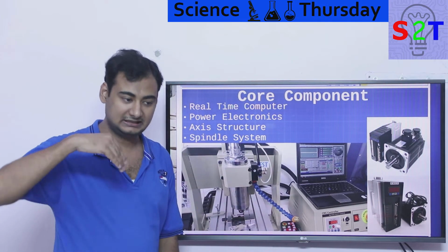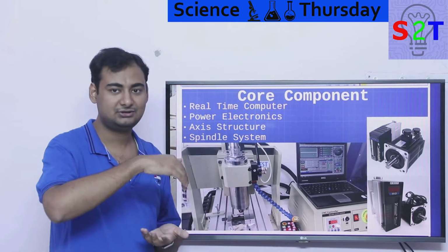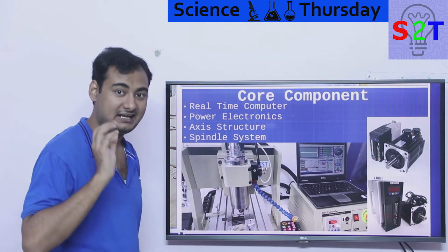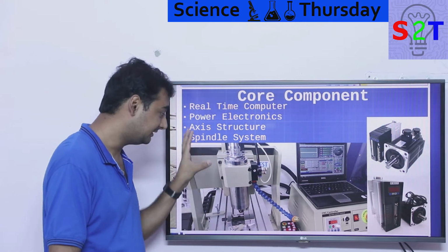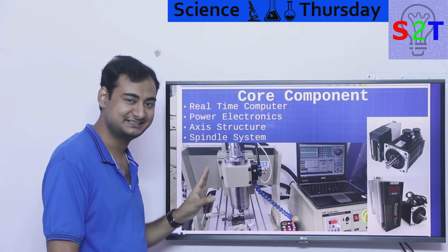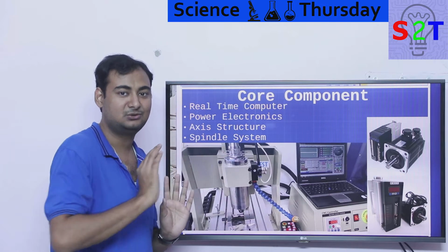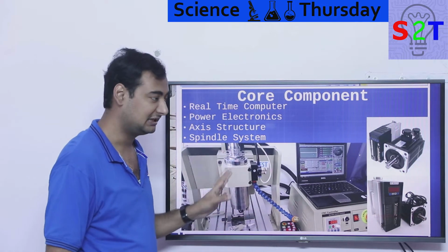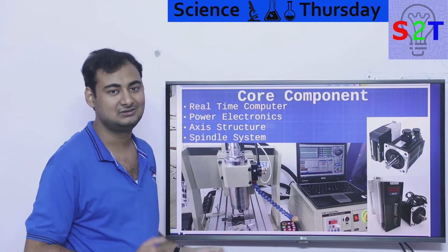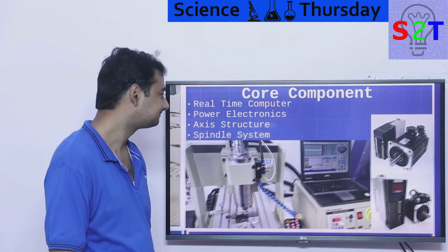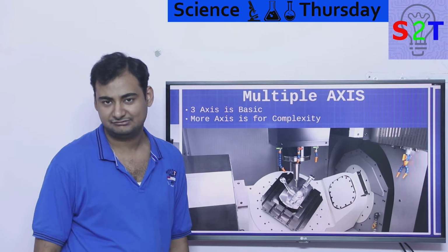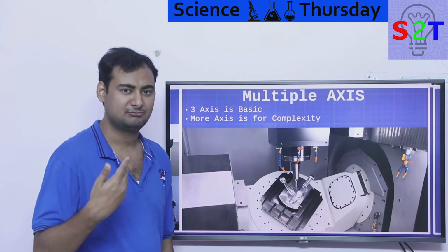After that, the final, the thing that actually does the work, because all you are doing right now is moving around. So what does the actual quote unquote cutting, drilling and things of that nature? That is the spindle system. Now spindle system is the most noisy part in the CNC machine. Basically everything else will sound silent compared to that. So people have now started to use what we call water cooled spindles, so the sound does not become like an ear blasting sound.